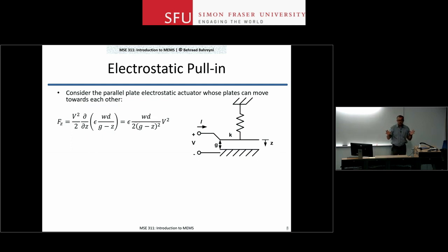However, I have bad news for you. The situation is actually even worse. You don't have that full range of motion. As the electrode on the top, the one that can move, is brought closer to the bottom electrode, you get a larger capacitance, right? And you get a larger dC/dy factor, meaning that you get more force.